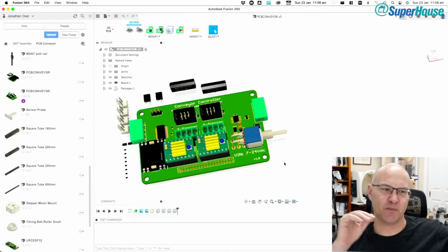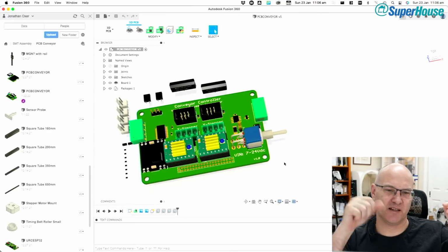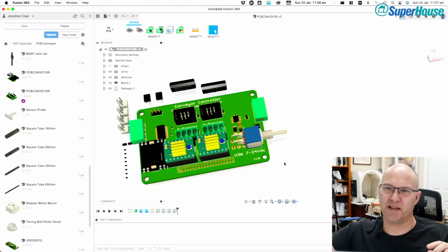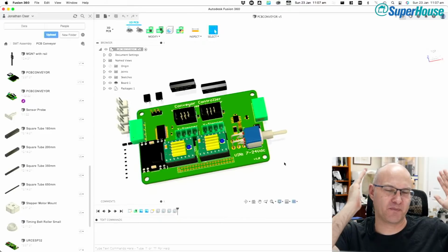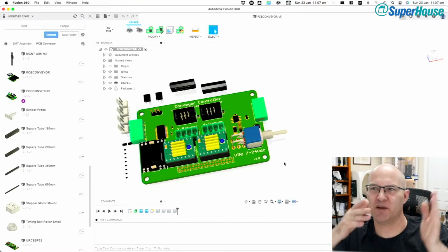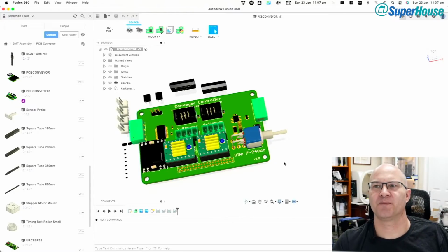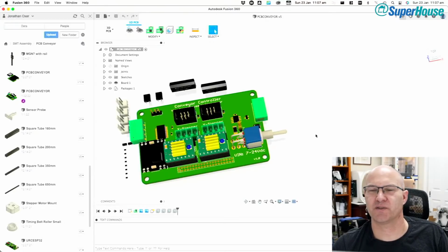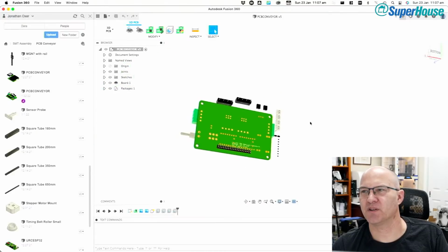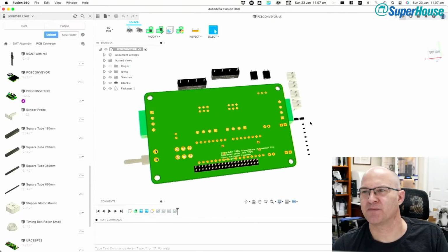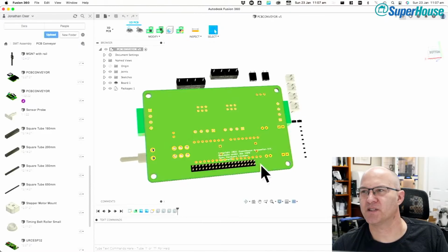So if I run cable into one device, and then I want to run the cable back down the frame and into the next device, I might have a few. So I'm going to have conveyor belt, then pick and place machine, then conveyor belt, then pick and place machine, then conveyor belt. It's a whole series. I don't want to have to run cable all the way to each one individually. It's easier to loop it around. Also, I don't necessarily know how people are going to be wiring this, so it might be more convenient to have power coming in on the right. We're actually looking at the back of the PCB here because it will go onto the back of the touchscreen like this. So the touchscreen would be in front of it and connected on this bottom connector.